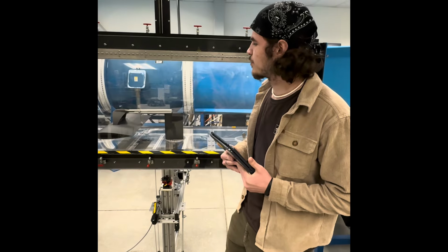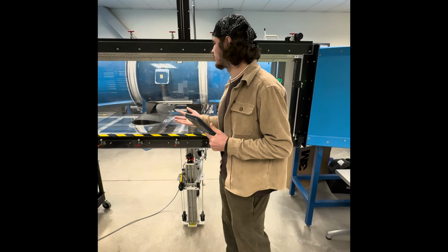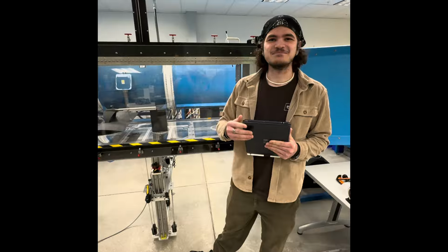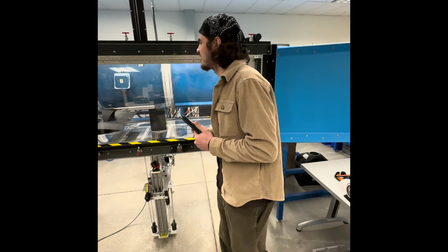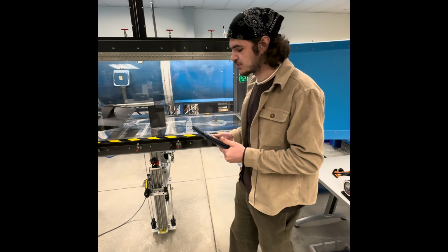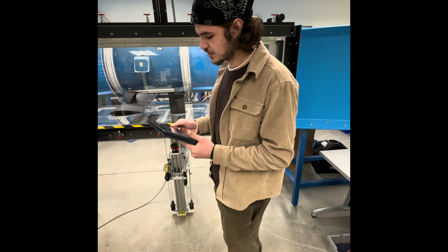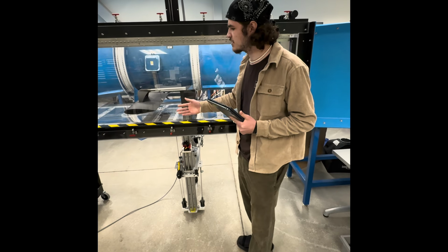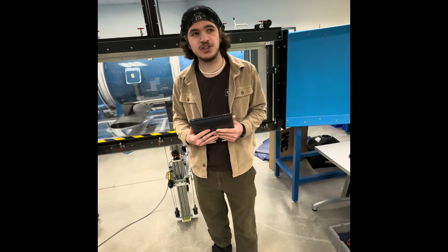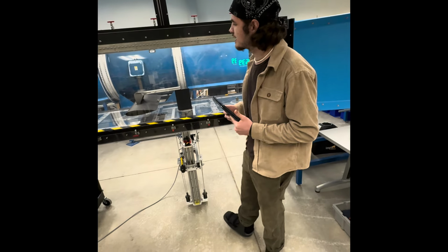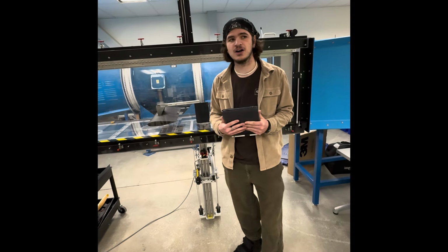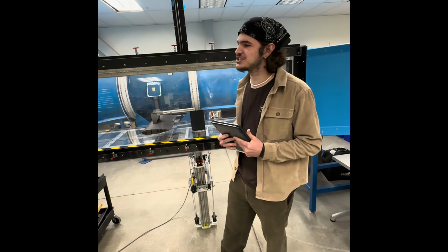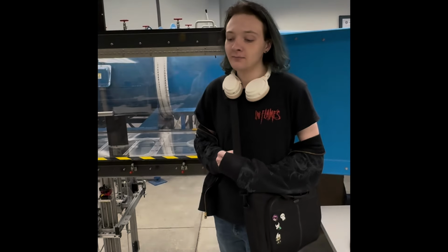Another area where we might face some error is our Reynolds number scaling using Buckingham Pi analysis. Some ways that we can help prevent error are consistent instrumentation, so just make sure that we are keeping the airfoil at the same height with each test, as well as trying to maintain a consistent angle of attack, as well as taring and calibrating our data.